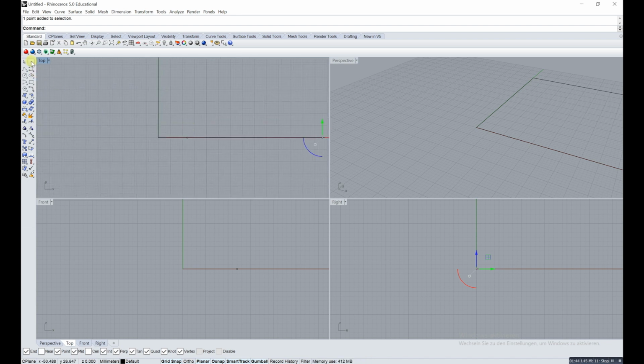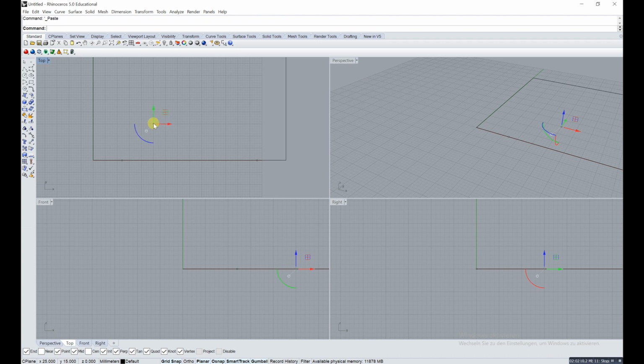So we get a point and we can just type the location of the point because we started at 0, 0: 25, 12. Press enter and it appeared here, which is completely right. And then just copy the point and move it 55, and then you should be on the outside. Yeah, you see you're exactly on the line. And now do minus 25.